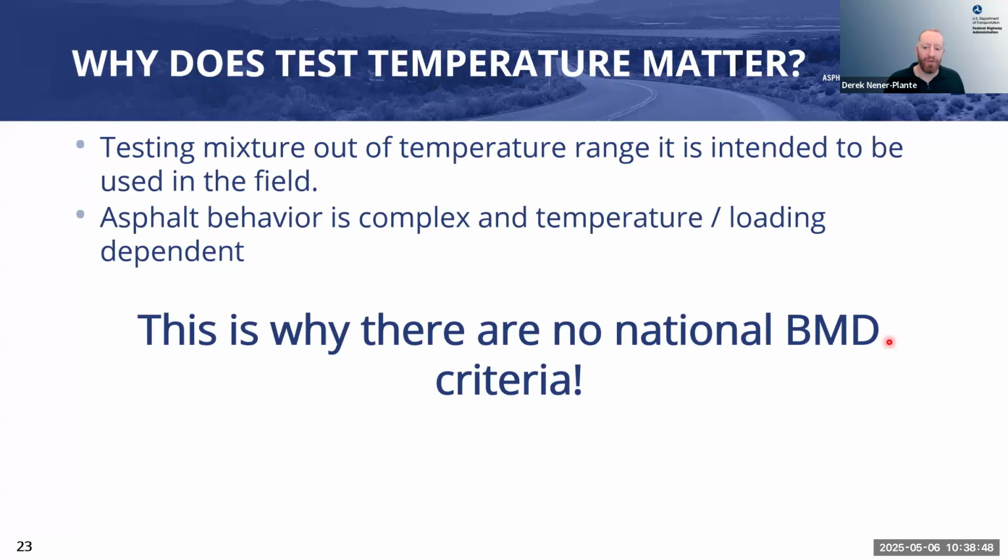I'm sure you've talked about it before: if we go back in time, we characterized an asphalt test by a penetration at one temperature. And we said, well, that one temperature doesn't necessarily predict that asphalt binder's performance at high temperatures, at low temperatures, at all these different frequencies and loading rates.